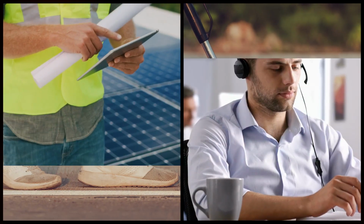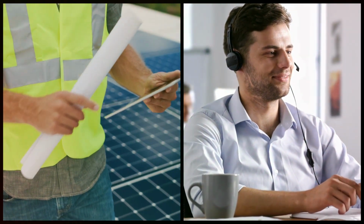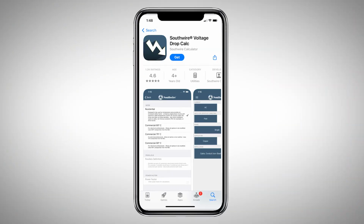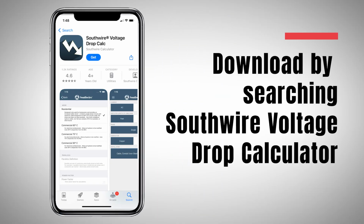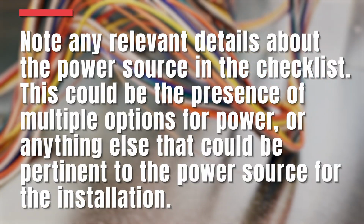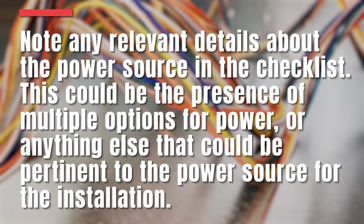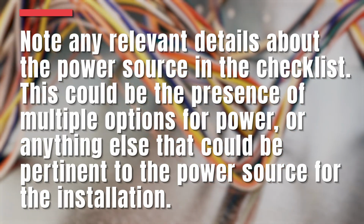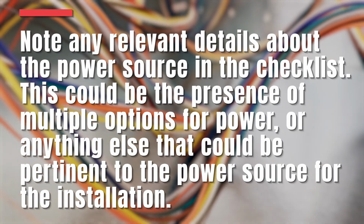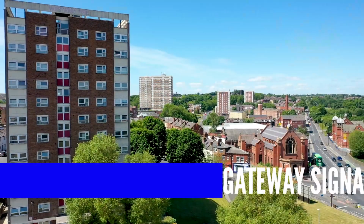With the assistance of the installer or the CellGate dealer technical support team, use the wire run calculator to determine the gauge of wire you recommend for this portion of the installation. You can download this calculator from the Android or iOS App Store by searching Southwire Voltage Drop Calculator. Be sure to note what gauge you recommend based on this calculation. Note any relevant details about the power source in the checklist. This could be the presence of multiple options for power, or anything else that could be pertinent to the power source for the installation.